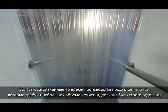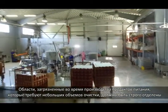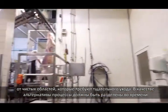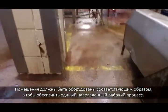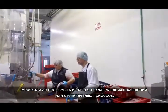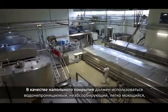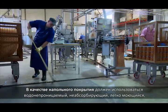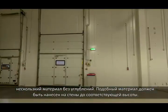Areas contaminated during food production that require minor cleaning volumes must be strictly separated from clean areas that require thorough maintenance. Alternatively, the processes must be separated in time. The premises must be respectively equipped to ensure one-directional workflow. Insulation of cooling premises or heating devices must be ensured. Waterproof, non-absorbing, easily washable, non-slip material without grooves must be used as flooring material. Similar material must be applied on walls up to the appropriate height.